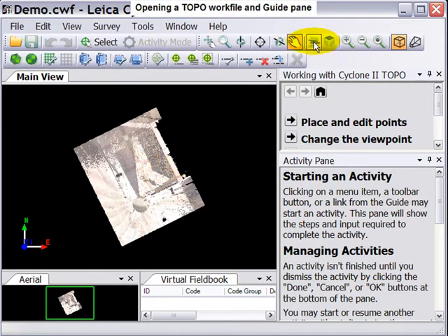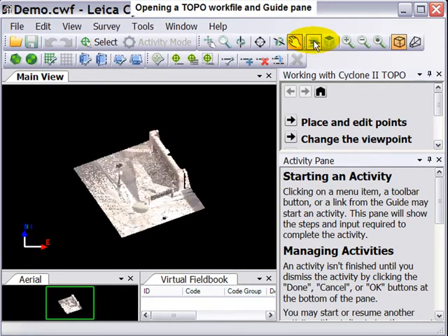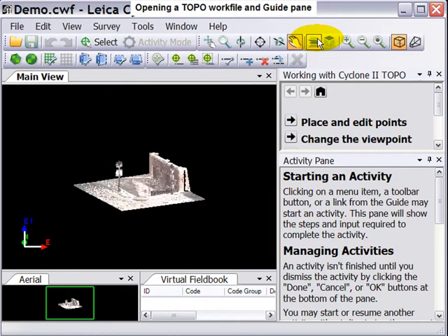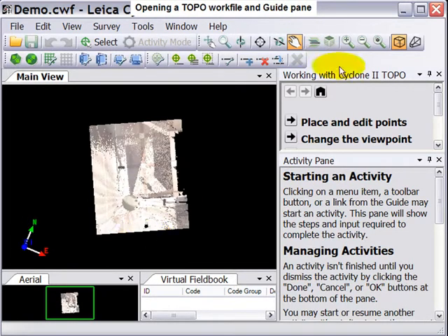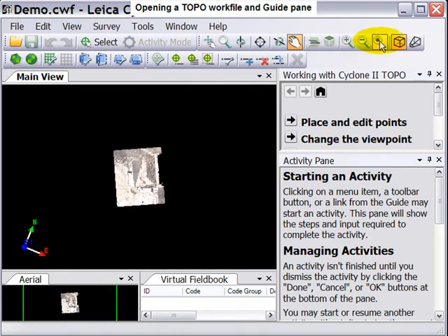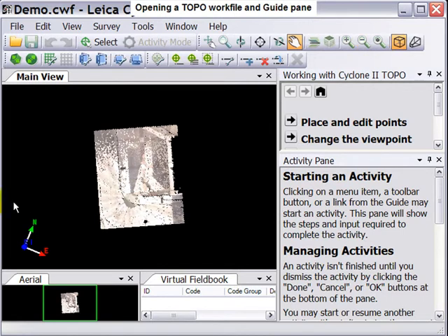You can also go to the next tilt angle. You can see the view tilt all the way to elevation. This is just a preset tilt instead of manually tilting yourself. There's a step zoom in, step zoom out, and there's a zoom all. So all of these functions together make it fairly easy to navigate around the point cloud.